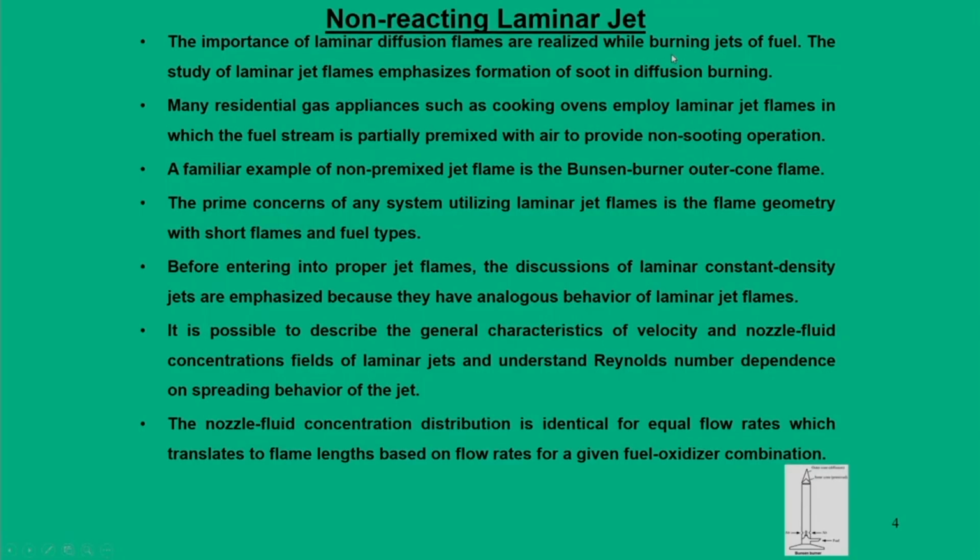So, let us start. The first thing is to give some brief introduction about non-reacting laminar jet. We will see that the importance of laminar diffusion flames is realized when we are burning jets of fuel. By burning jets of fuel we mean, for example, when the fuel is injected through a nozzle, like a fuel injector in a diesel engine. In such cases, some diffusion flame is generated. Basically, when a diffusion flame is generated, it means that the fuel and air mixture is pre-mixed to some extent, and when the jet comes out, it tries to get the remaining quantity of oxidizer from the air.